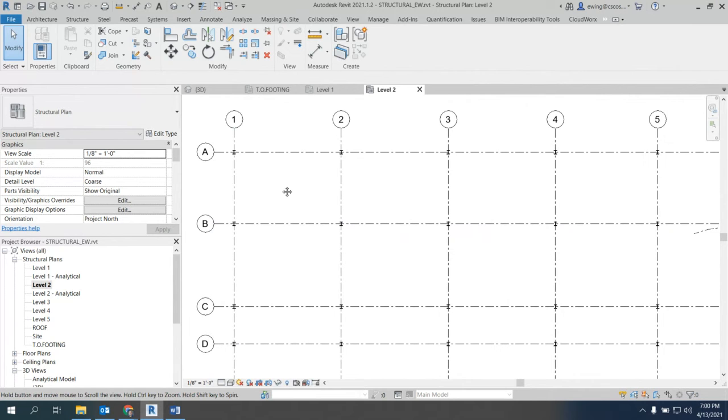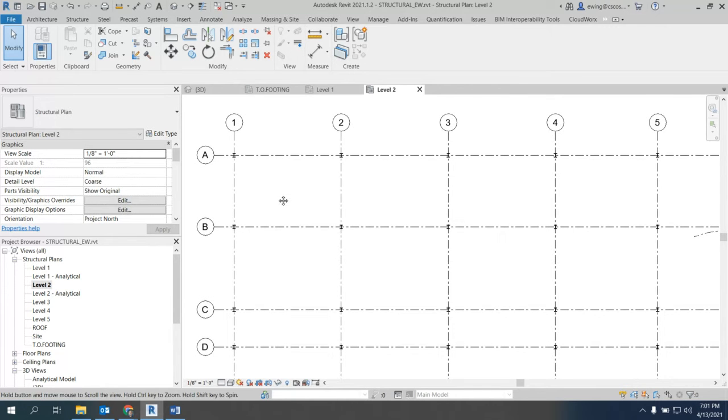Great. Now, structural framing plans are very boring looking. It's just a line with a piece of text on it. That's all it is. But back when we used AutoCAD, that's all it was. Right? It was just a stupid line with a piece of text that meant nothing. We're going to actually put in a wide flange beam, right? And we'll see it in 3D, and that text will be active. It knows if we change that beam, the annotation on that text is going to update, right?